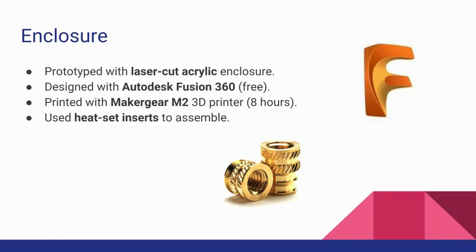Then you stick your soldering iron into it, which conducts the heat through the brass and slightly melts the PLA or whatever it is you're using. You go into it, you pull it out, and it solidifies. And then you get an actual nut that you can screw into many times, because otherwise people are tempted to make a hole that's just the right size in PLA, and you do that like 4 times and it strips and it doesn't work anymore. So that was super cool, and we used them all over the place.